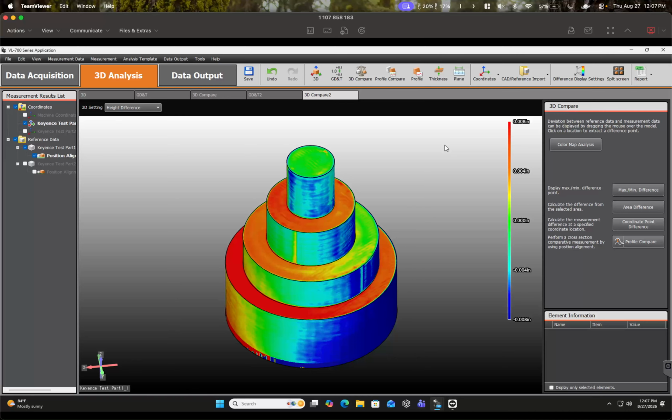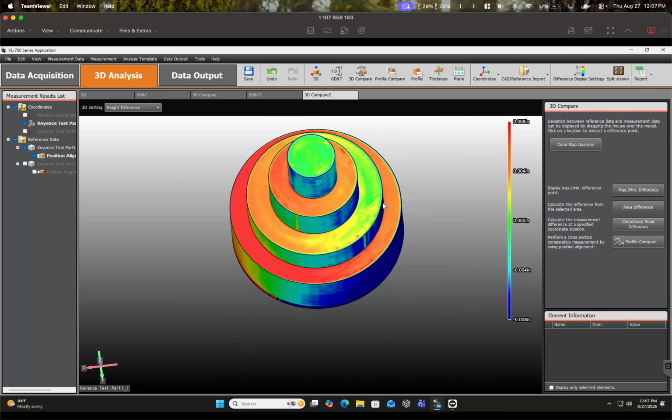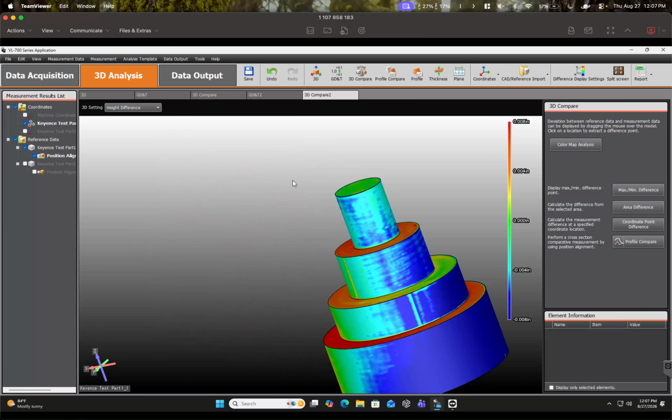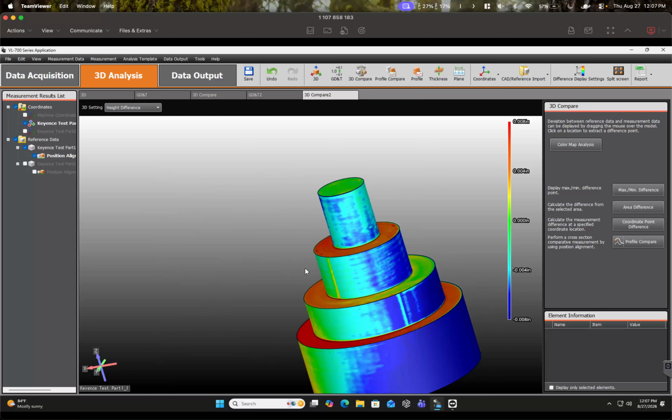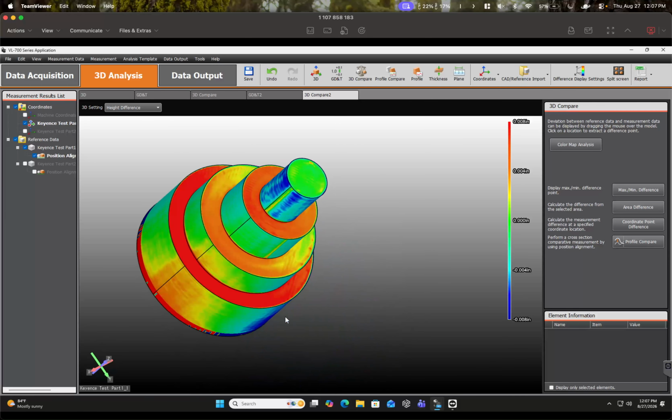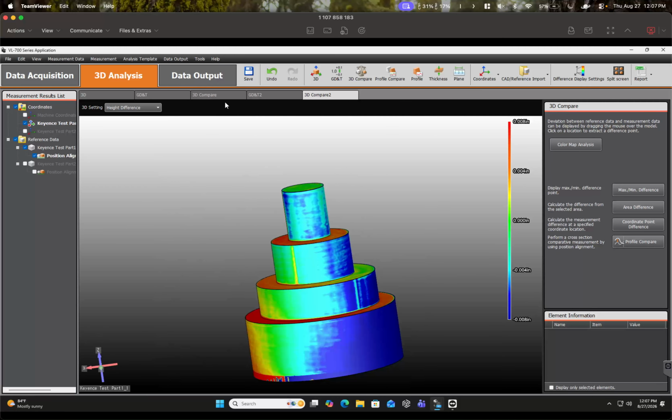So we're within 1/8 of an inch. That's pretty good for 3D print. I mean, for an FDM print like this, that's fine. Like I was talking about, the Z seams, you'll notice these little stripes of inaccuracy that are pretty consistent. That's to be expected with a 3D print like this. Anywhere that is green is dead on, anywhere that is blue has more material than is needed, and anywhere that is red has less material than is needed. That's everything for taking measurements off of the 3D scan and comparing it to a reference CAD file.